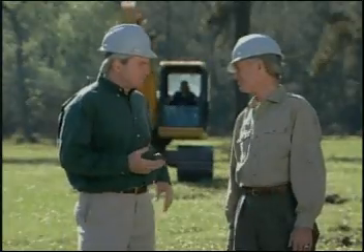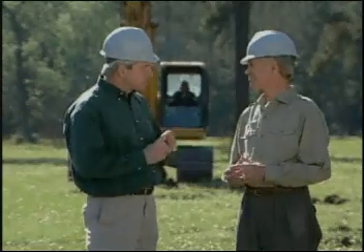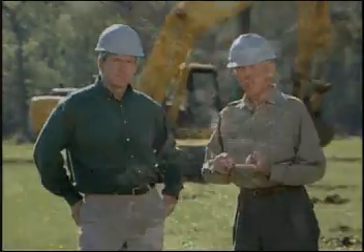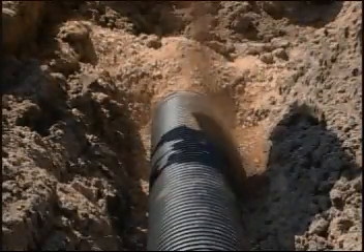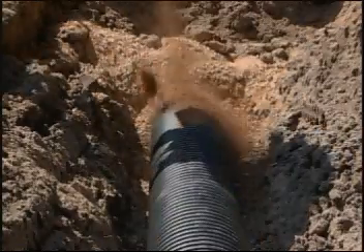Bill, this might be a good time to explain the differences in embedment materials, placement, and compaction. When the contractor installs flexible pipe, the structure must be built in the trench. This often means replacing the excavated soils with higher strength select granular materials such as crushed rock.